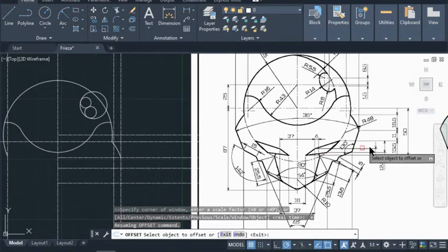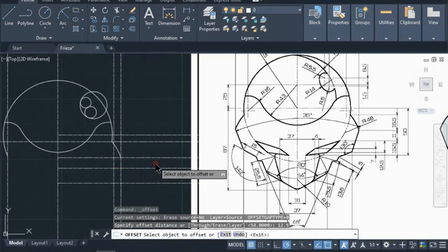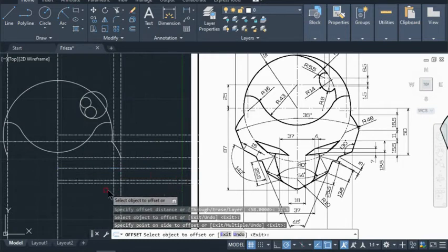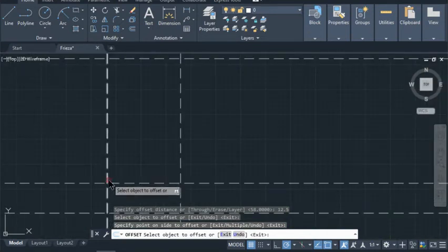All right. We don't have the 12.5 offset in here yet, because we got the 50 down and then we go up 15, 11, 57. So we got all that. We don't have the 12.5. So the 12.5 offset is actually from the 15.5 going down. So it's this one right here. So we have to offset that one first. So offset that to be 12.5, enter, and then select this is the one that we're going to offset. So that is the one that we're looking for. All right. So the drawing is going to be from there, and it's going to be somewhere just above this location.